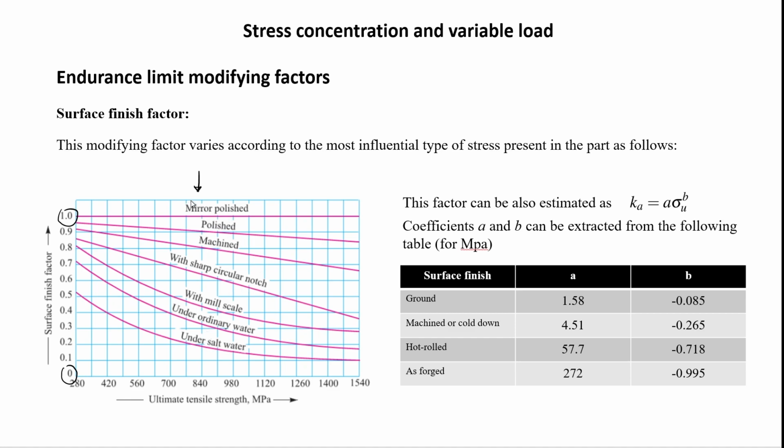And you say, well, all my designs are going to be mirror polished. Then you have to ask yourself, is it necessary to have mirror polish? Because this is very expensive. This costs money to do. And maybe your part is not possible to mirror polish, because it's inconvenient to do it. And if this is costly, then well, polished or machined, whatever the part is. So it's a decision you have to take.